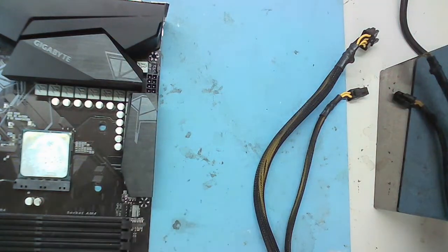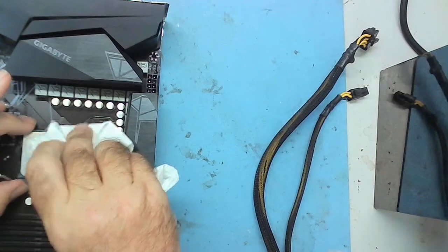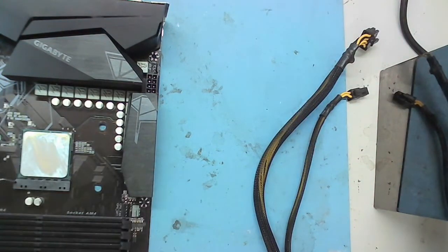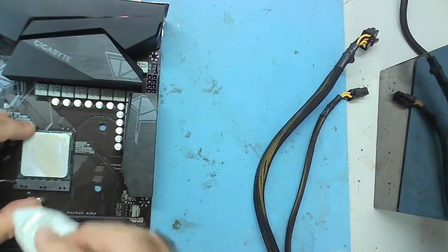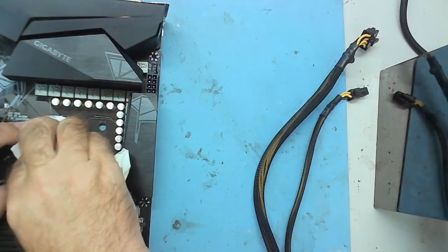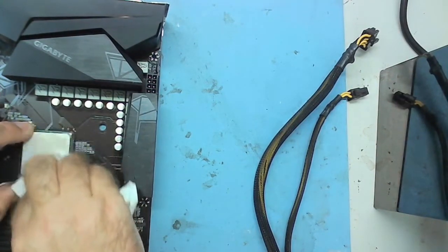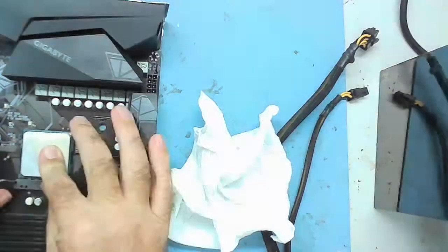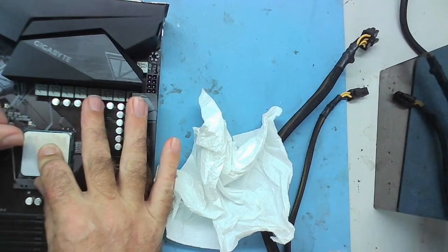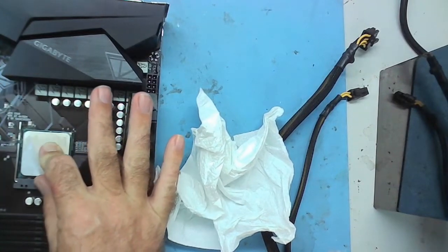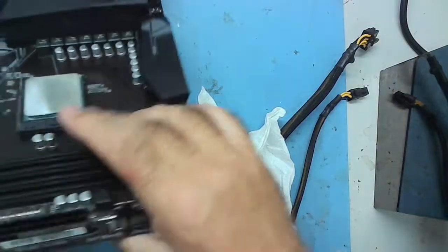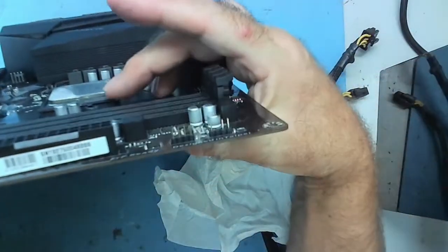Let's just clean the heatsink compound off it a little bit, because I want to put my finger on it and push downwards, at the same time as I operate the socket lever, and see if it'll actually grip the CPU. This one, that's a good enough reason for it to be faulty. Okay, just pressing on the CPU and I push down on the back of the socket. Right. It clicked. The back of the socket's lifted up a little bit.